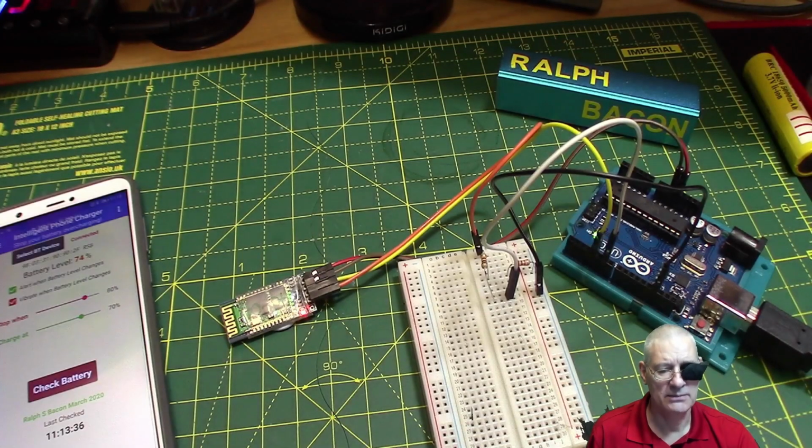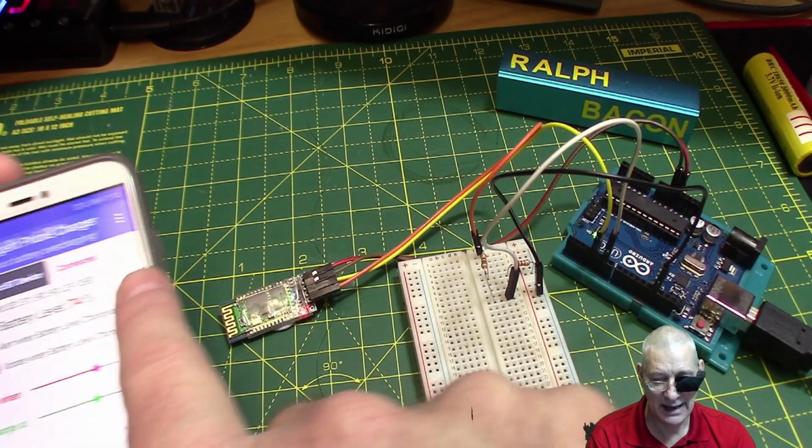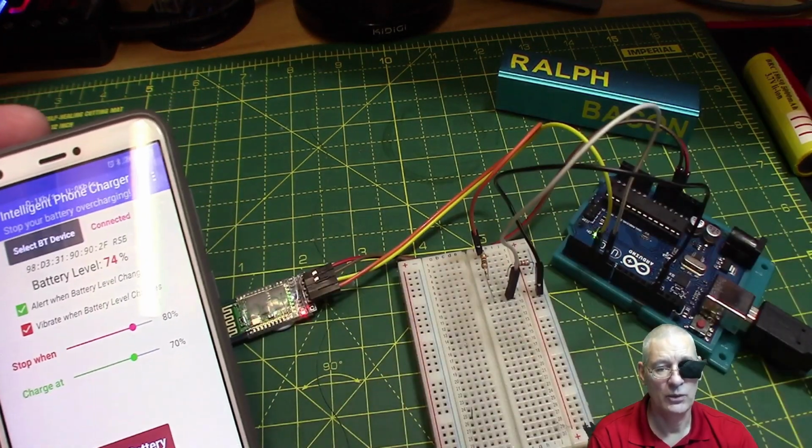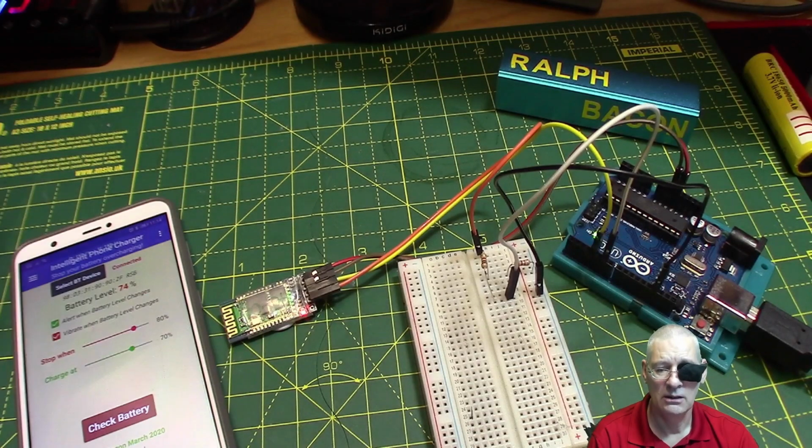Right, let's have a look at the very simple Arduino sketch, which is based on the one from video 37. You basically wait for a connection and then you just receive stuff. You go, is there anything for me to receive off that Bluetooth device? Oh, okay, I'll take it. Now, because the value of the battery is between 0 and 100, we can just send a one-byte short integer, a uint8_t, not a double, not a standard integer, because that'd be 2 bytes.